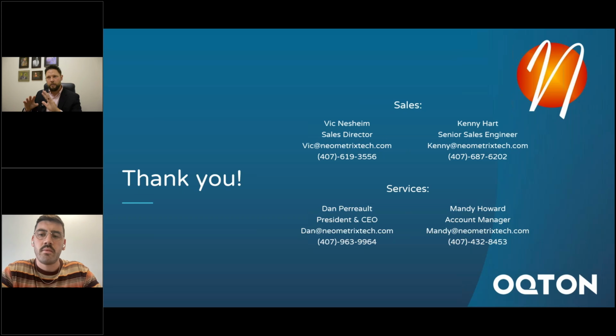Gotcha. Yeah. On my Design X overview slide, the scan is actually kind of sparse. As long as you have all the data you need to replicate the geometry, let's say on a revolve or a pattern feature, or even a surface where you've got relatively most of it and there's a big gouge in it, when you go to model it, you can basically ignore that area and use the surrounding geometry, or geometry in another spot, to replicate it. It's a similar application. You only need to scan as much as you need to gather all the information and make sure you can place it correctly.